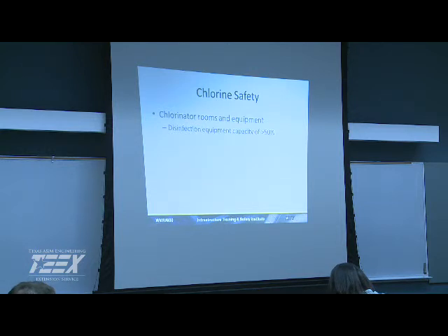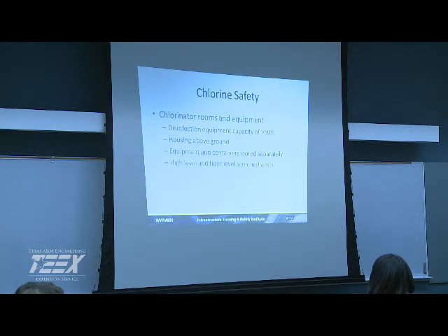Talking about safety, we need to keep our equipment segregated, keep our chemicals segregated properly. When you look at your feeding capacity, you're supposed to have 50% greater capacity than your highest demand at your peak flow. And that's the way we need to gauge our equipment. You want it above ground, especially if you're using gas, because it's going to settle, so don't have it down in a basement or a little sump area. Got to keep things separated.